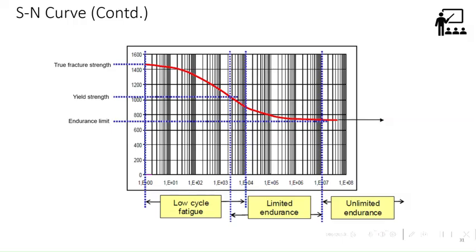The endurance limit is that during testing. But when you make a component from the same material, it undergoes so many processes, chemical process, technology process, then machining and all. So that affects the endurance limit. Okay, sir.